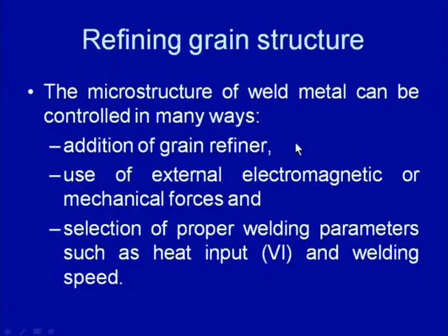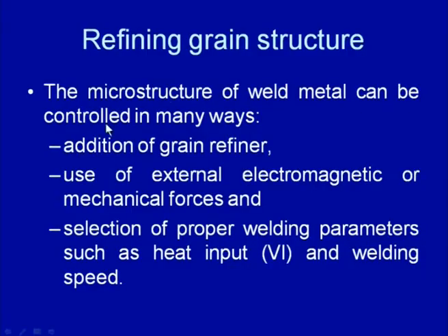So, the refinement of the grain structure is the approach which is used to control the solidification cracking tendency. We have seen that the coarse columnar grains increase the solidification cracking tendency. So, refinement of the grain structure, especially with the equiaxed grains, helps in developing significant resistance to the solidification cracking tendency.